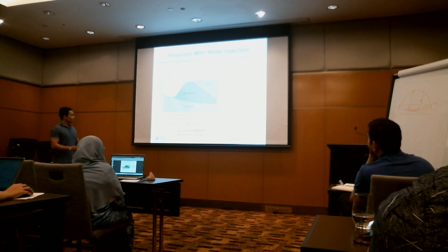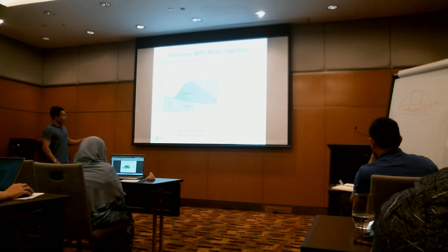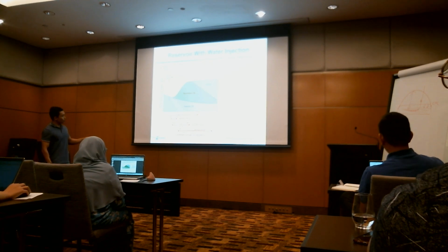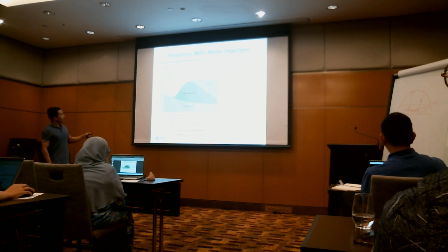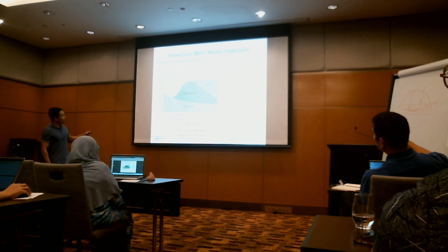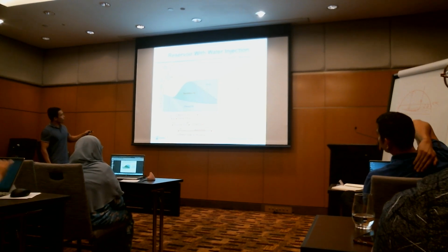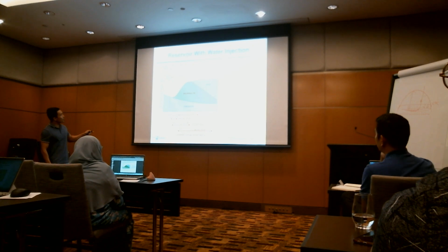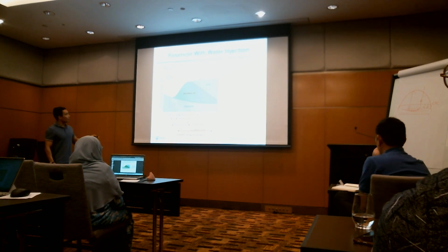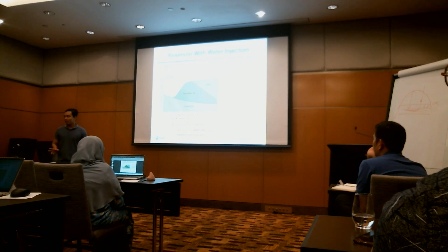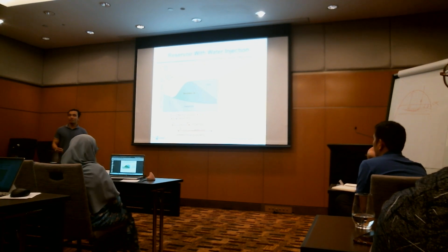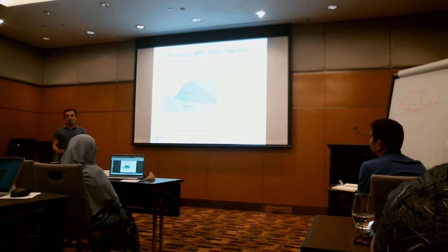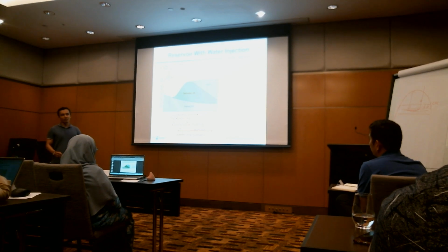Okay. So in this field life, you can see that as the field declines, you start the injection from point A. We call this the initial field life. Normally within this duration, you won't see the impact of the injection yet because it is trying to replace the voidage, the volume that you produce.